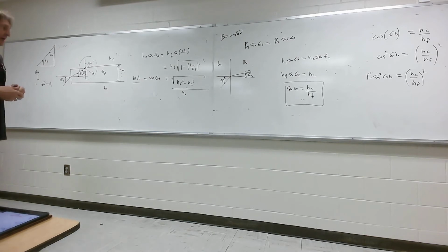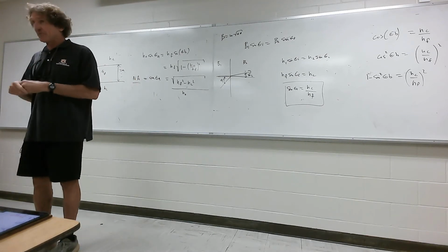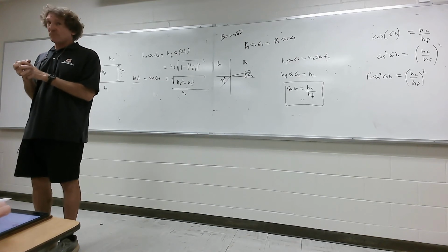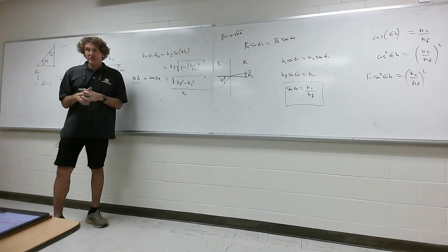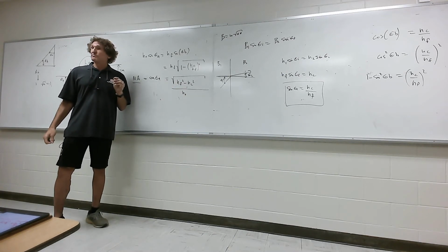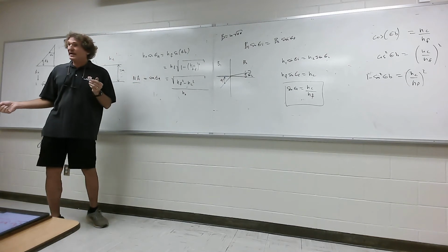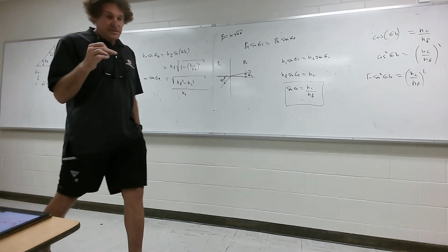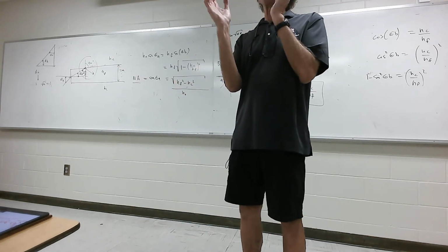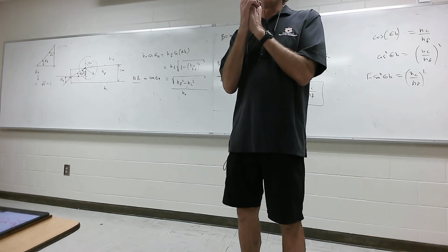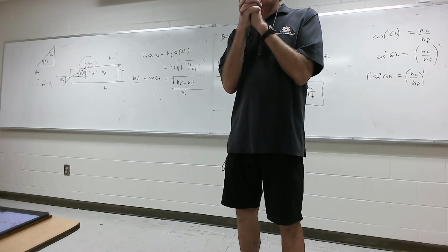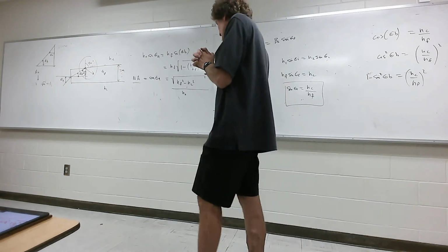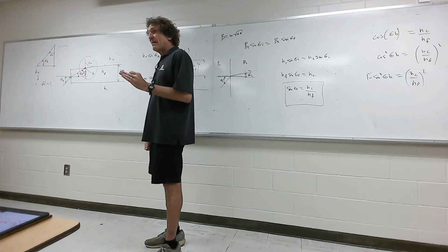So the numerical aperture, the way I like to think of it, it's really a measure of the goodness of the fiber. The smaller that is, the harder it is to work, which tells you intuitively that you would like NF to be as much different than NC. It would be nice if NF was sort of twice NC. Y'all follow me? Then you'll get a big angle. That ain't the way it works though. With fiber optic materials, they're made of a core of glass, and they add dopant, and there's not a lot that they can do with this. There are very small differences in NF and NC. So that angle is inherently small. And that's the real thing about fiber optics, this numerical aperture. That's so important, to have it large enough.